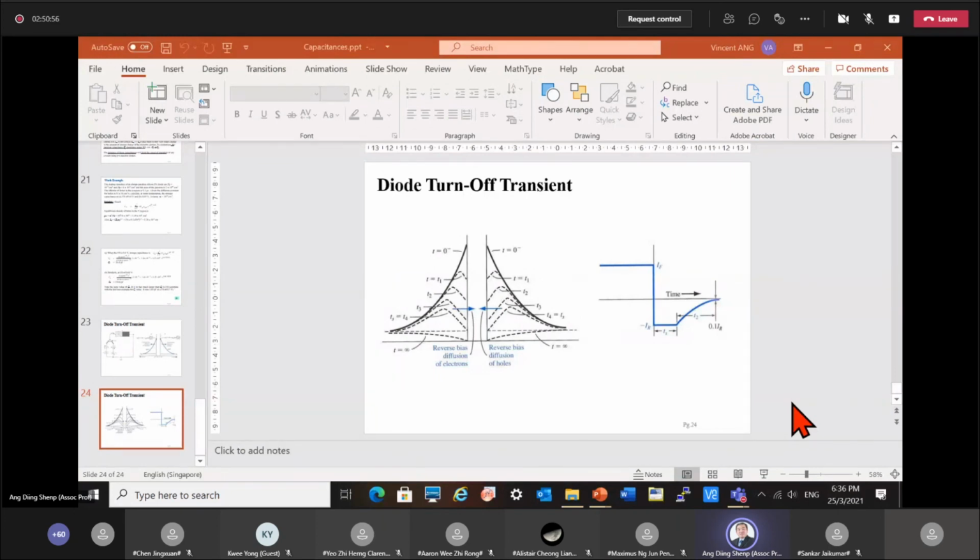But the moment forward bias is reached, where carrier injection happens across the junction, the further increase in the current will be controlled predominantly by the storage capacitance, because this is much larger compared to the junction capacitance. Okay, I get that. Thanks.